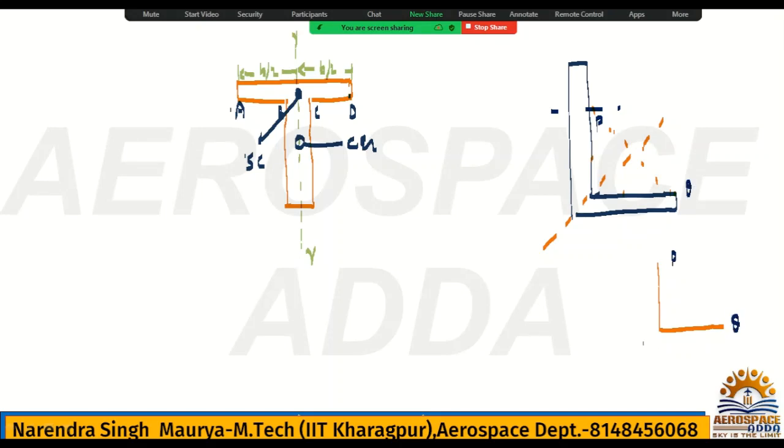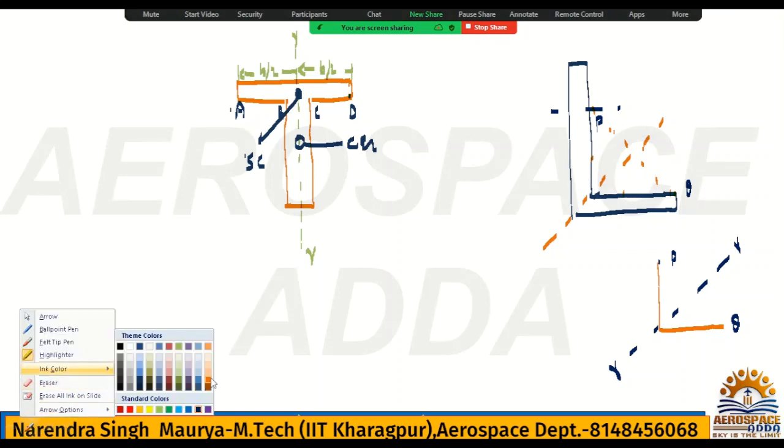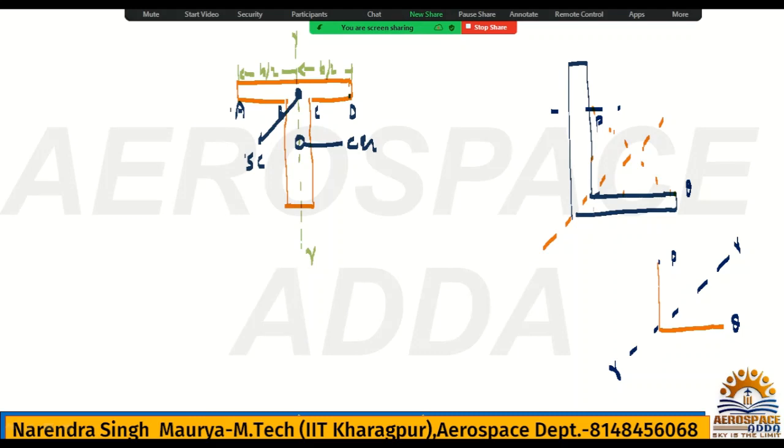Now you draw one axis here. Say this is the R axis. About R axis, this P and Q, if you overlap this, then P will overlap to Q. So about the R axis this portion will be symmetric. So where is the chance of the shear center for this L section? You can say it will be here, somewhere here. So the shear center will exist at this point. Hope you understood by this diagram.